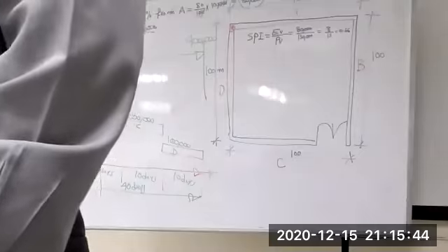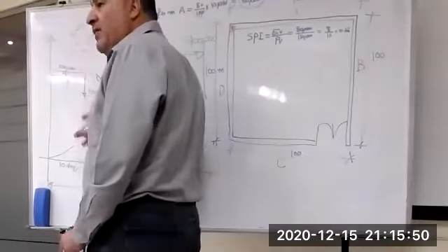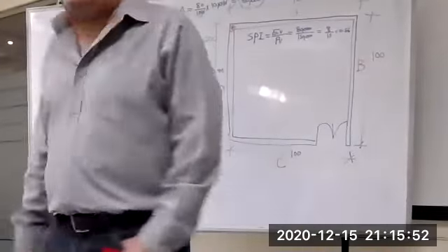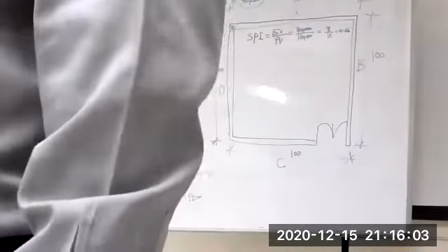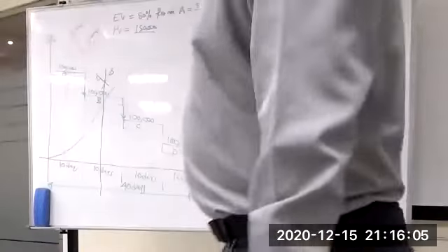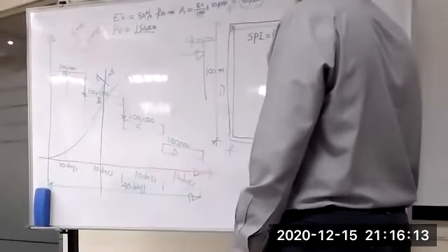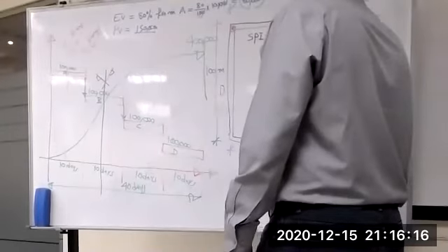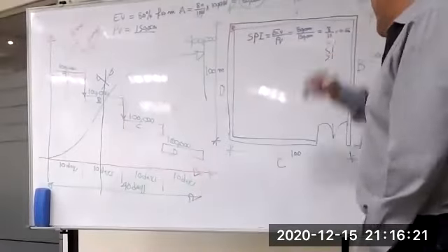What does it mean? You are behind schedule. How many days behind schedule? You are behind schedule 2 days here and 5 days here. That means 7 days. You are behind schedule 7 days. This is a different term. And you are progressing 56% of your planned achievement. That means you are behind schedule. Is it less than 1 or not? Equal to 1, less than 1, more than 1. Equal to 1, you are as planned.